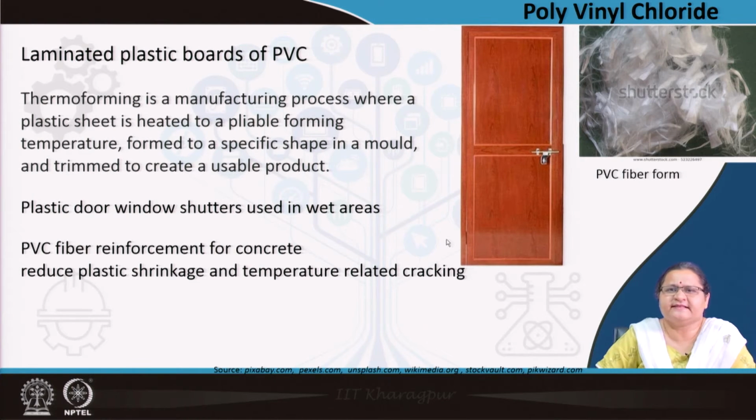Here you see PVC in fibrous form. It can be used as a reinforcement in concrete, which reduces shrinkage and also temperature-related cracking. So, if you add PVC fiber into concrete where large changes of temperature are expected, then PVC fiber is a good answer.